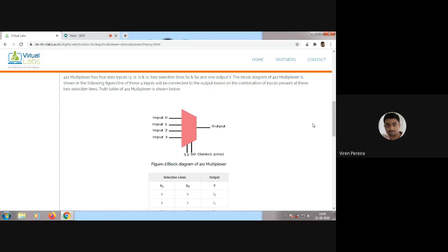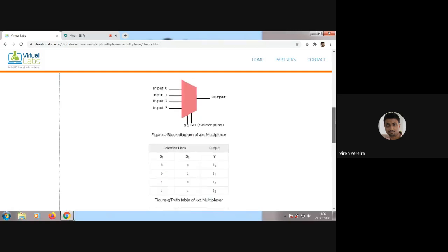You all got what I'm saying, guys? Then I0 will be reflected at the output. If 0 1 is given here, then this input will show at the output, no matter what the value. If the input is 1 here, it will show you 1 for the second condition. If the input is 0 here, it will show you 0. If the input at input 0 is anything, it doesn't matter, it will take the input from input 1.